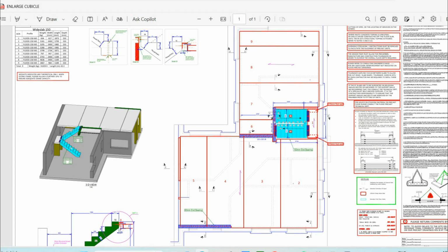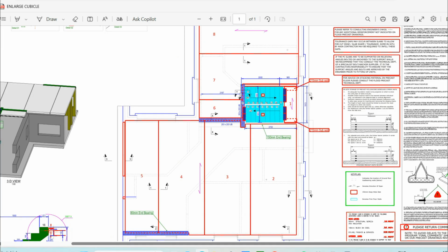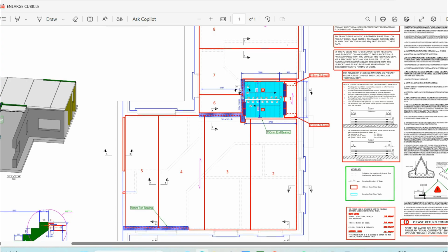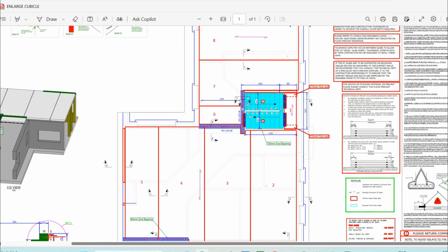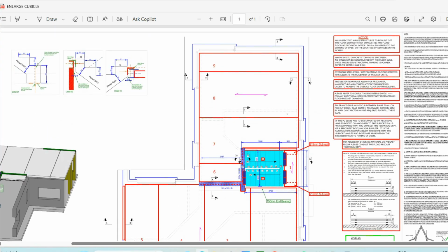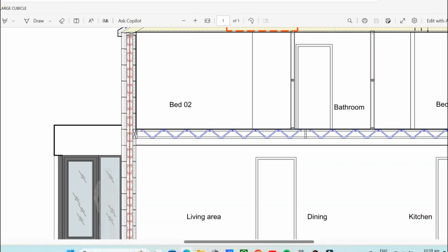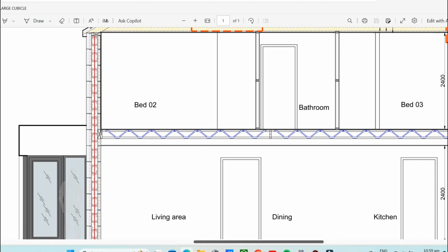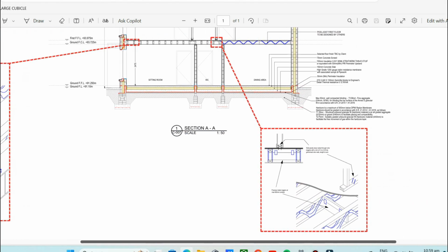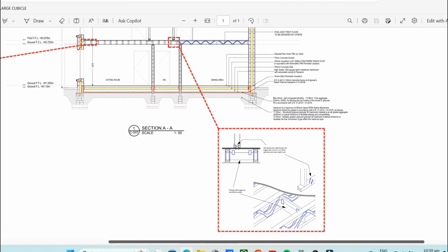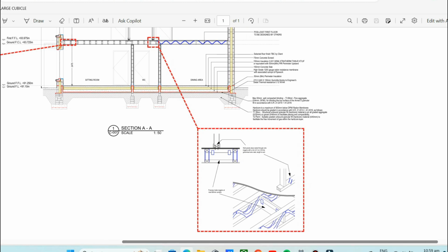In most cases, as you know now, we put in the precast flooring as shown, with the directions of the spans. Now this can come from one of the manufacturers in the area who supply the concrete floors, or we can estimate which way the shortest span of the floors would be. In general, when you're doing steel or timber, you might use posi joists, but if you're doing concrete, the loading is much greater on the openings.